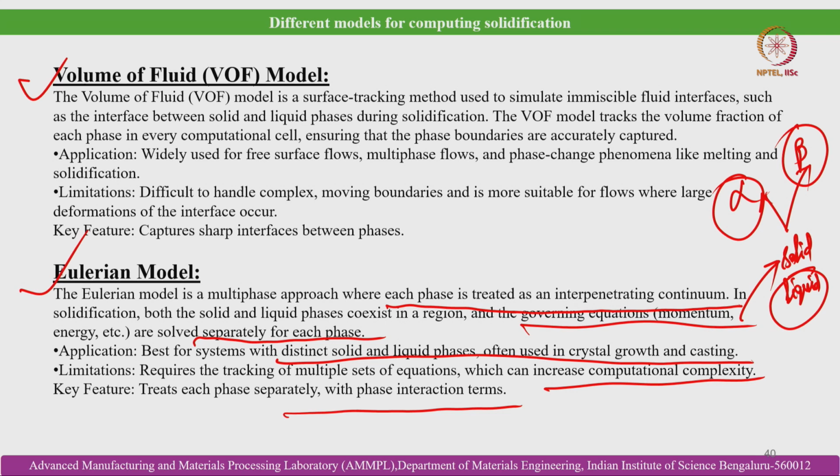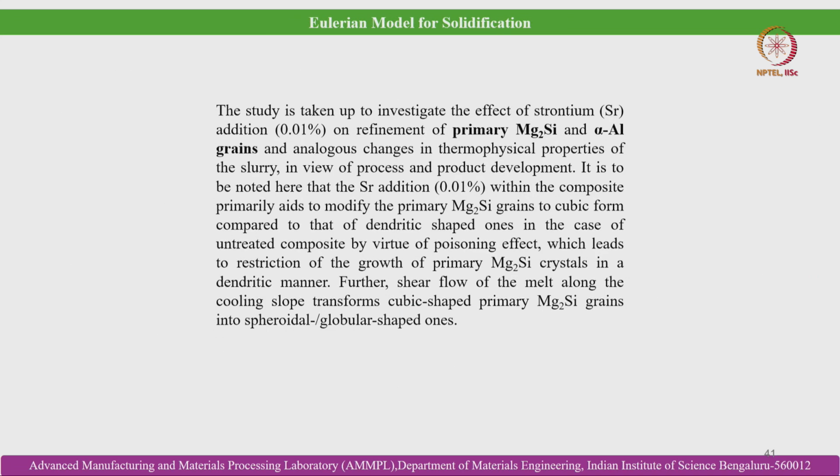Also, separate interface tracking is not required in the Eulerian model, like we discussed in the VOF model, because we are solving individual equations for individual phases. They are assumed to be interpenetrating, so a volume averaging technique is considered in the Eulerian multi-phase flow modeling technique. Now let us discuss the case study.